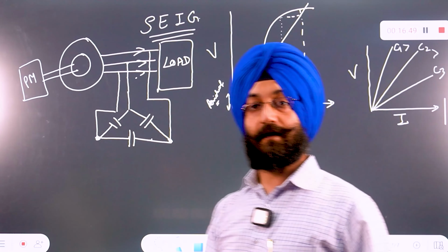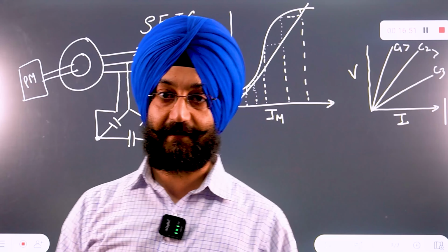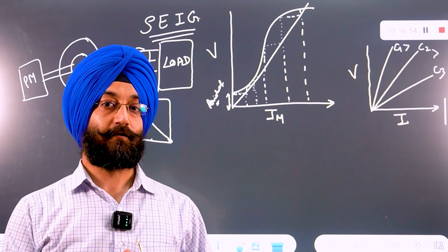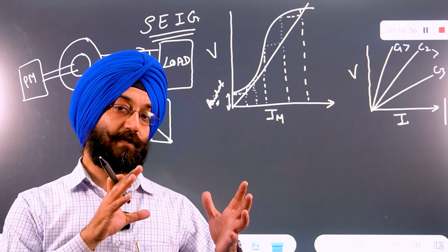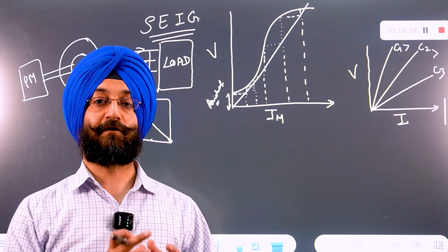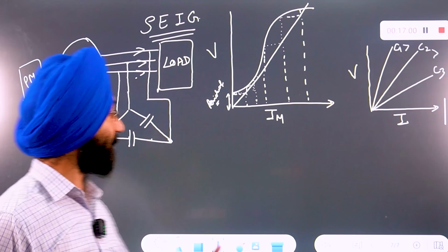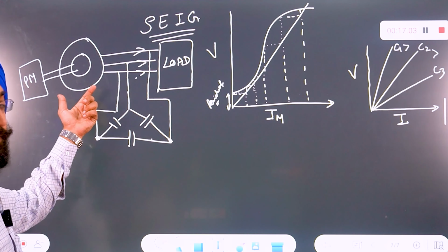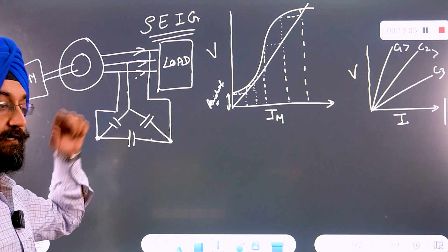After that, the capacitor at its full efficiency gives the maximum current or voltage to the stator windings, which is needed to develop the rotational magnetic field. So with the help of the capacitor bank, the rotational magnetic field can itself be generated in the induction generator.